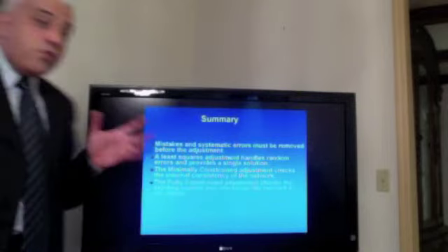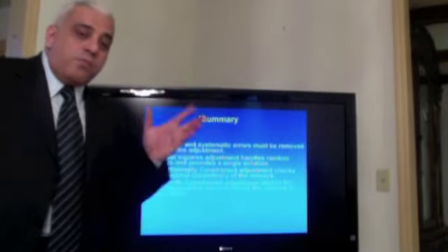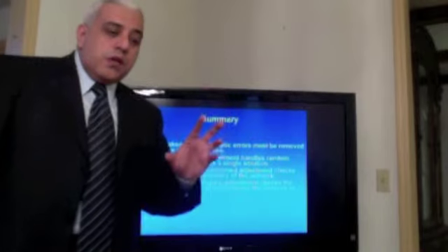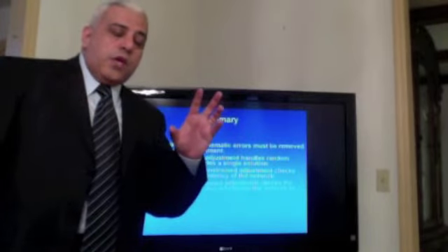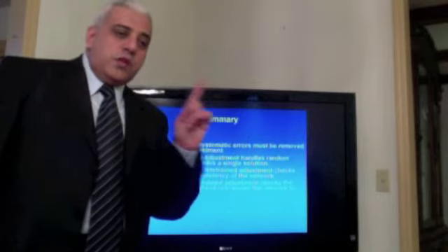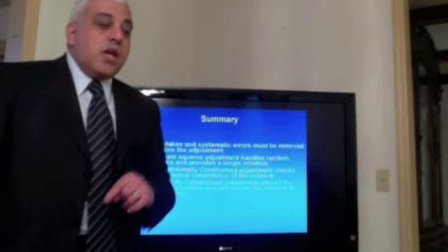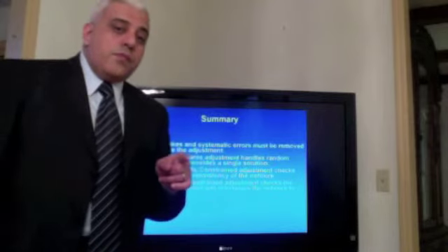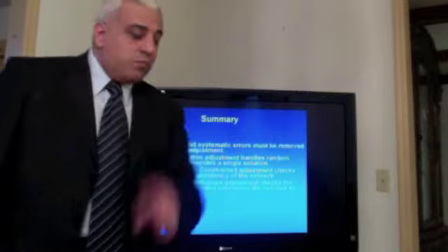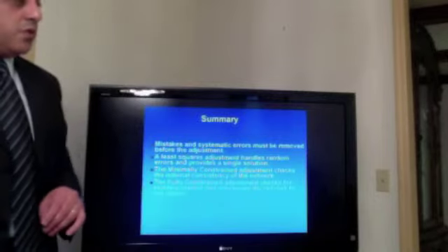And in fully constrained adjustment, we transform from WGS84 to local. We also reduce the spherical coordinates to a certain projection, and we also adopt a proper geoid model to adjust the third component too.